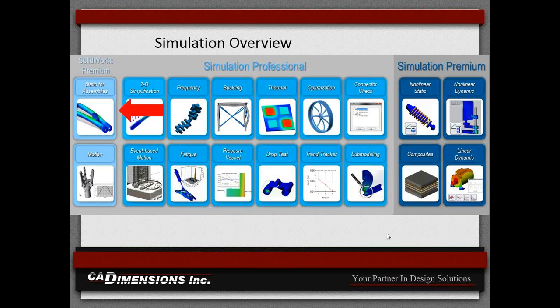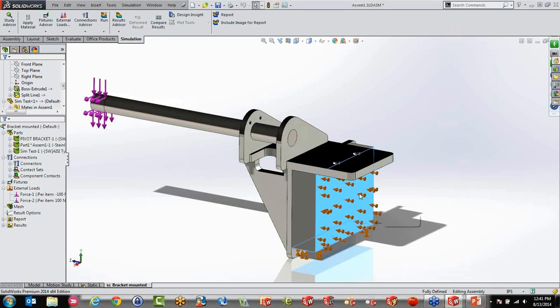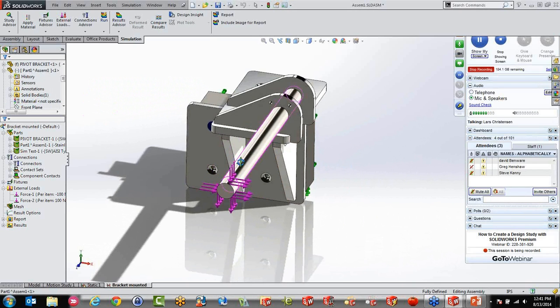A question about being inside an assembly: I made it, but then I added the bolt connectors to it. In SolidWorks we mate things together, kind of like a refrigerator magnet: coincident, coincident, coincident. You saw me do that. But the simulation software is almost like doing physical testing in real life.